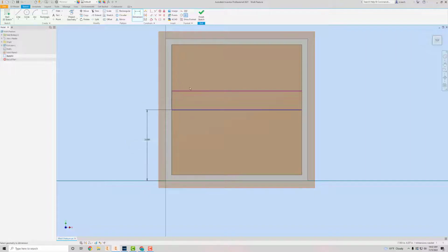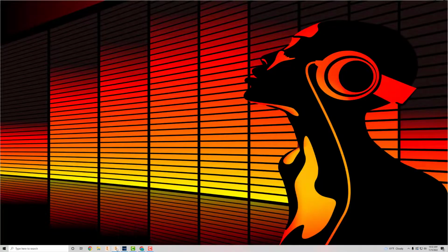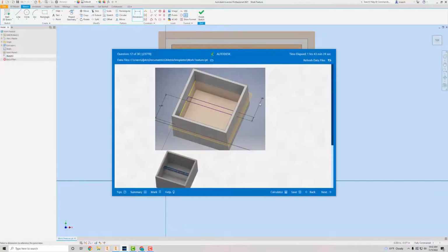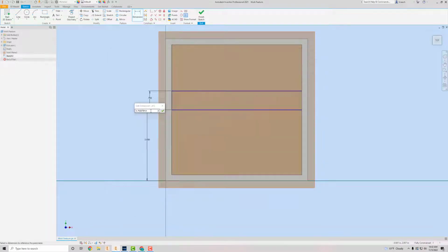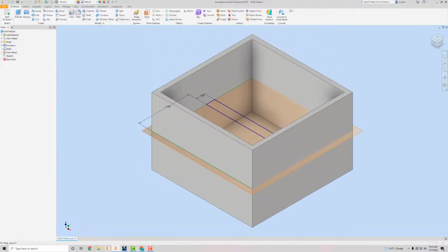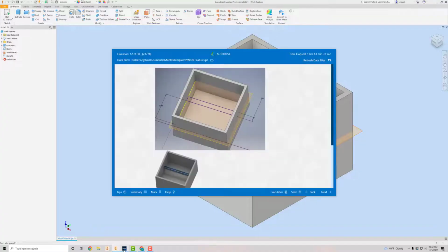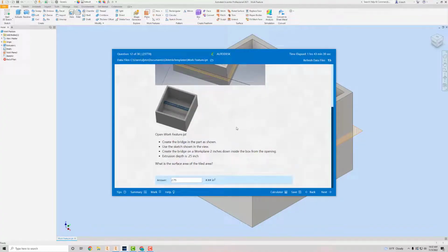And then this is gonna be, where am I at? Where am I at? The 0.5. 0.5. Hit that. And then I want to finish that sketch. I want to extrude it, extrude depth of 0.25.